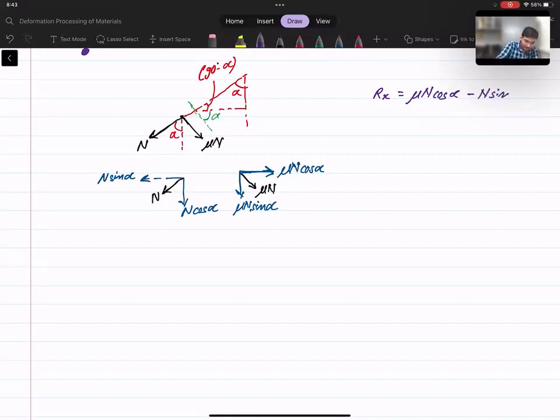We can see from the resolution of loads. Okay. And to take the material without slipping into the rolling setup, this Rx should be greater than or equal to 0, because if it is less than 0, so total reaction force or resultant will be in the left direction here, and the material will get slipped. It will not be pulled.